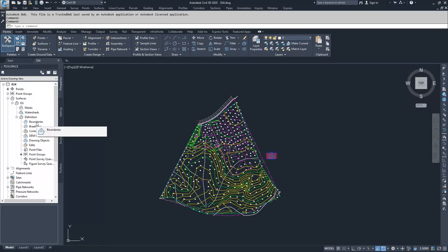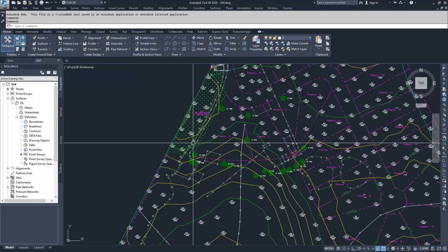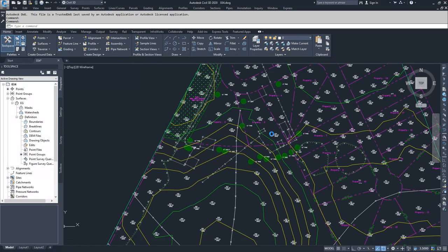Like we know that you wouldn't want to show contours running through a home. A home is generally usually built on a single level foundation. So it wouldn't be appropriate to be showing contours running through a house. So that's what we're going to do in this drawing. We're going to actually add boundaries for the couple of buildings that are shown in our topo.